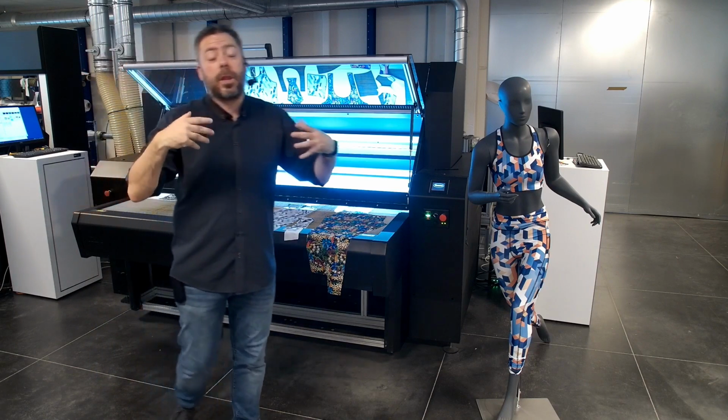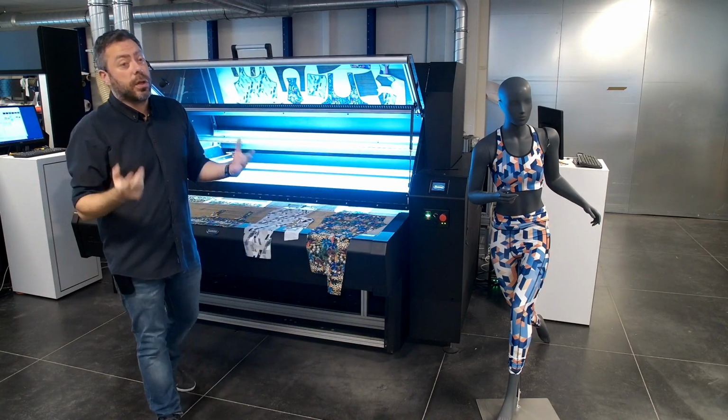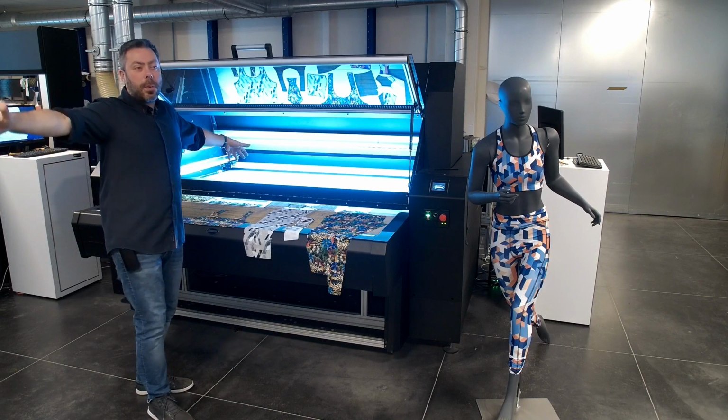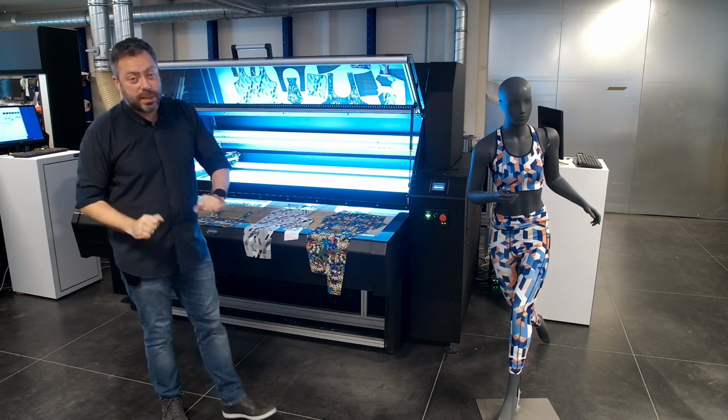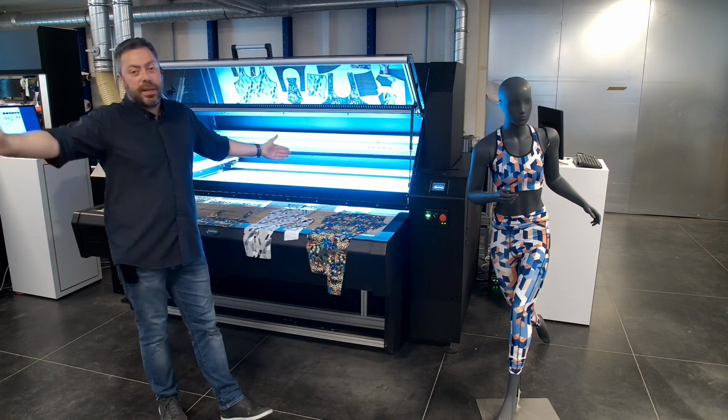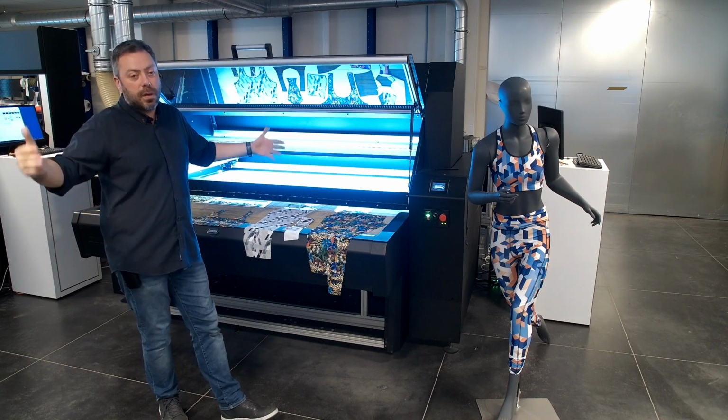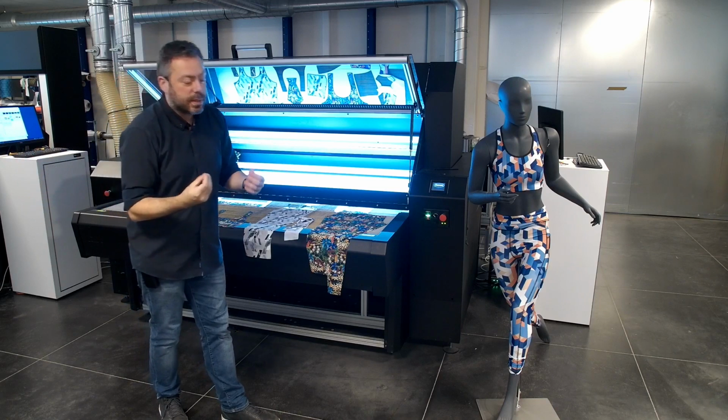If you look at a lot of textile cutters, they generally have a very long bed, and that long bed defines your largest nest. So if you have an 8-meter long bed, you can have an 8-meter long nest to optimize your nesting.